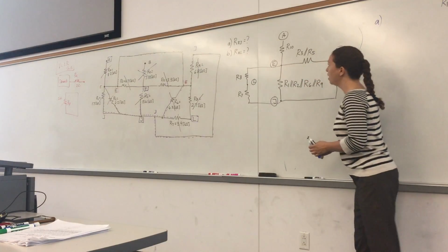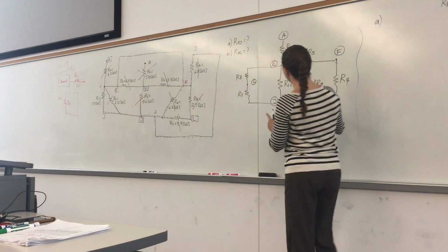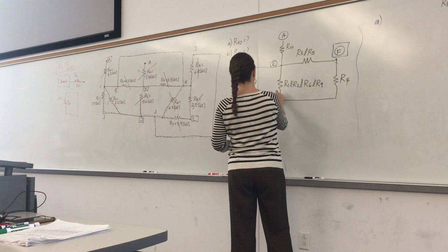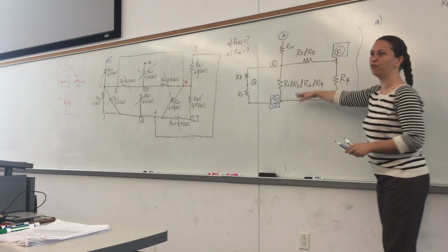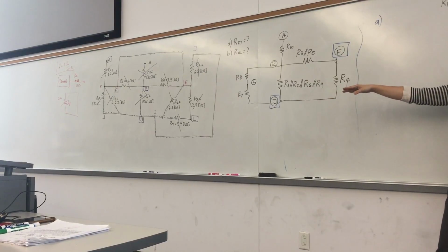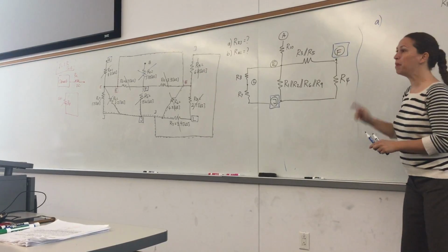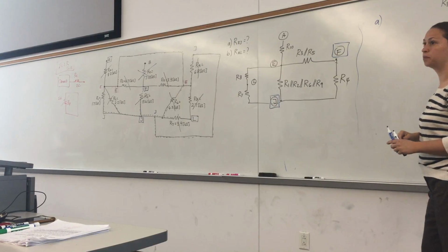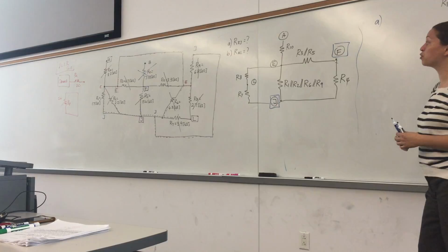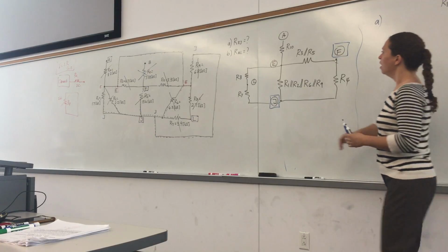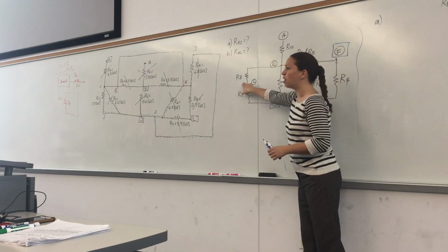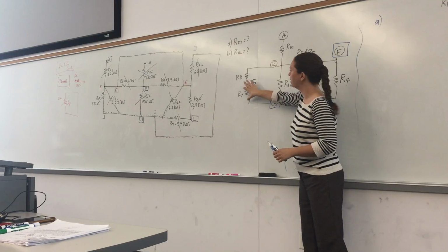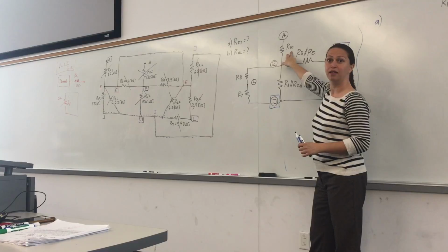Okay? Now, part A, all of my interest is in F and J. I really don't care about any of the other nodes. I can lose them. Okay? So, based on that information now, what can I do here? Combine which one? You can combine R7 and R8, which loses L. Do I care? I don't. You can do that. What about R10?